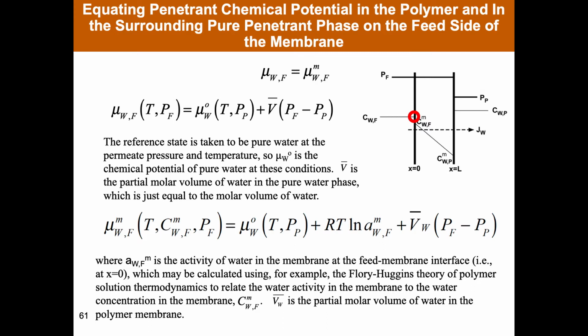And so now imagine what's going to happen as we raise the feed pressure here. As we raise the feed pressure, what's happening to the chemical potential in the water? It's increasing, just linearly proportional to whatever that feed pressure is. What's happening to the chemical potential of the water just at the surface, dissolved in the surface of this membrane that's also exposed to that pressure? It's also increasing.